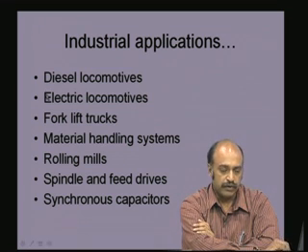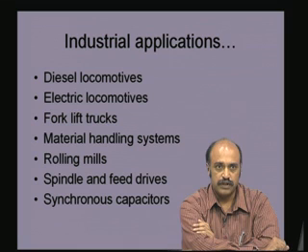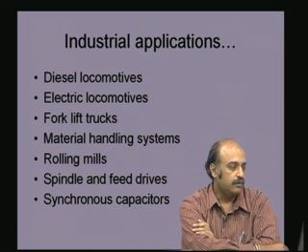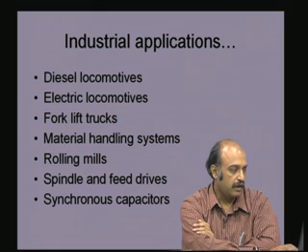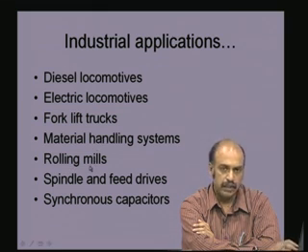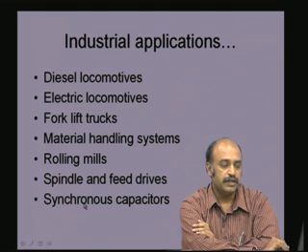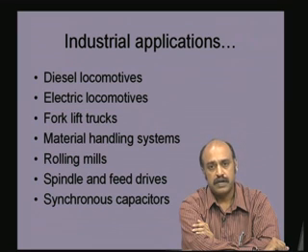The electric locomotives, the forklift trucks, which you would have seen are battery driven, DC series motors which generate high torque to lift heavy loads. The material handling systems, rolling mills, spindle and feed drives and lathes and CNC machines, the synchronous capacitors, which are nothing but synchronous motors used for power factor improvement strategies.